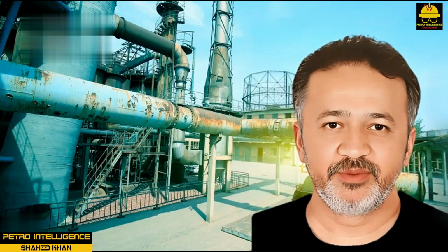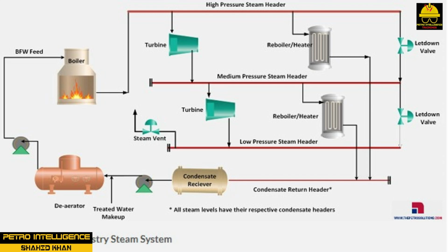High-pressure steam system, 400 to 800 psig. HP steam is supplied as required by lowering the pressure from the SHP header. High-pressure steam extracted from steam turbine drives can be used to feed the HP steam header. HP steam may be imported from other units into the high-pressure steam header to maintain overall steam balance.